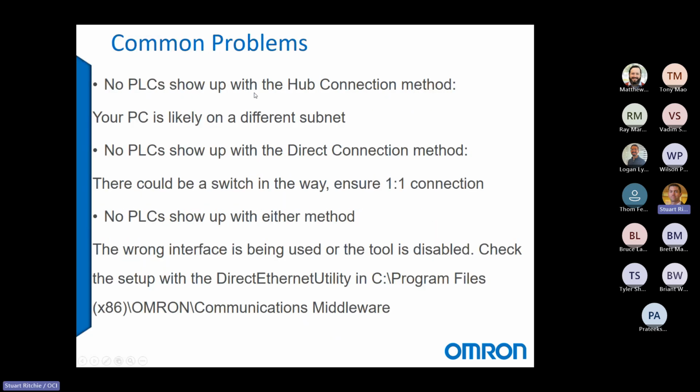Now, the tool does not always work. I've had a lot of phone calls of people having some issues with it. So some common problems that we run into are no PLCs show up with the hub connection method. Now, this is usually when your PC is on a different subnet. The switch will not route the traffic properly, or it'll block the protocol altogether.